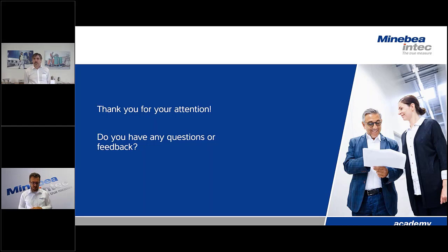You have a reference sample and you put it on the scale, remove it, and put another sample which you compare with. And the accuracy is given with the reference sample, not with the scale. And in this case, the readout doesn't matter. The accuracy of the readout is not necessary, but it has to be always the same result. And the comparator scale is actually the best example for very good repeatability, but could also be poor accuracy.